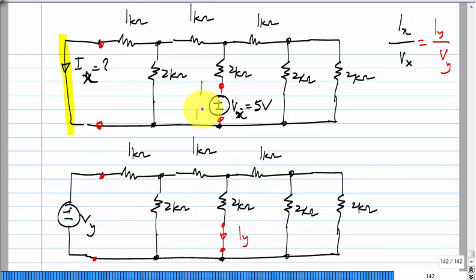If I call this 1 prime, then what I am looking for is Y21, right? Except of course, if this is 2 prime, I2 would be normally taken as going into the 2 port, and Ix is actually minus Y21 times Vx, okay? And similarly here, this is 2 prime, 1 prime, because I took minus Y21 Vx, I should also take in the same negative direction to the normal 2 port convention, okay? So, the point was to apply that.